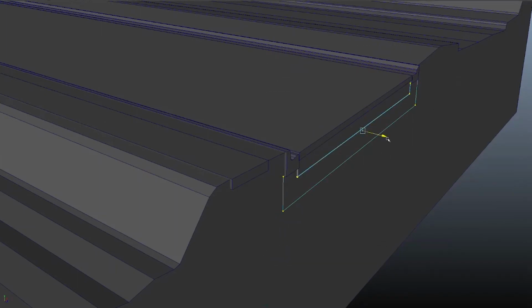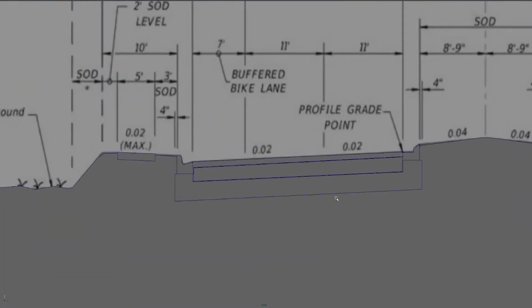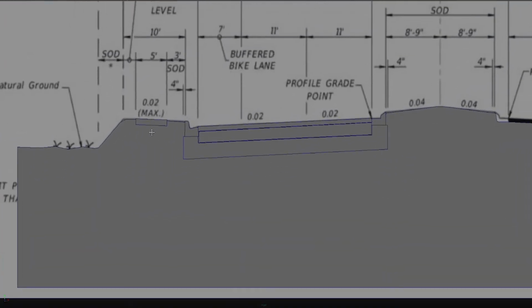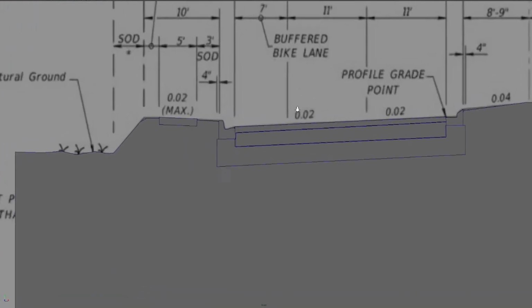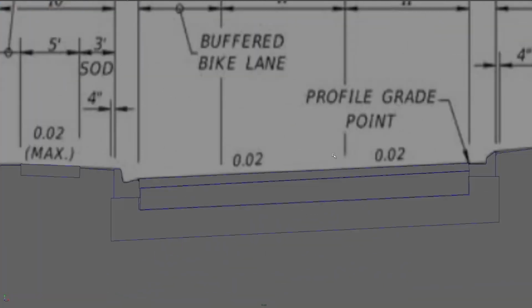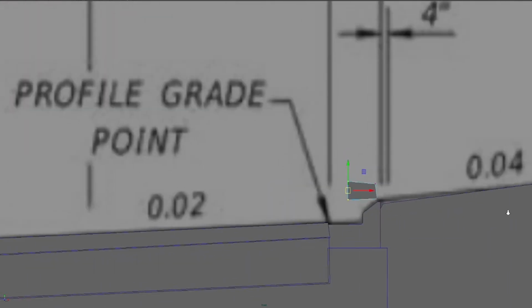Just pull those forward a little. That way everybody's visible. Okay, now that we've gotten our main shapes out of the way, we need to create the striping. So since we have already created shapes, why recreate the wheel? Let's go ahead and take this road that's already been extruded, duplicate the geometry, and then just push and pull the points and turn it into a stripe.